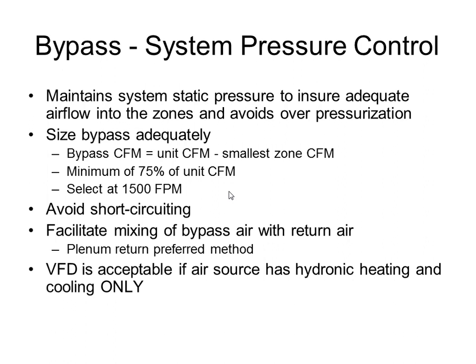VVT systems, like we mentioned before, one of the names was constant volume zoning. You can actually do a VFD application with a VVT system. It is very possible. The only issue you run into is if you have a VFD on an air source, you need it to have modulating heating and cooling. You need to be able to back that VFD down, but also back down that heating or cooling so you don't burn a coil or freeze a coil.